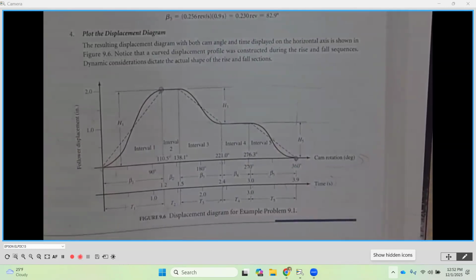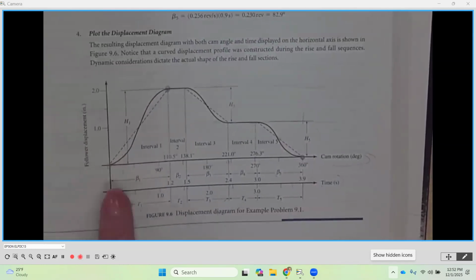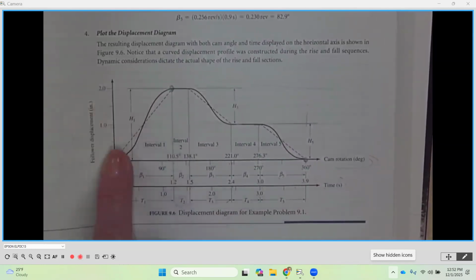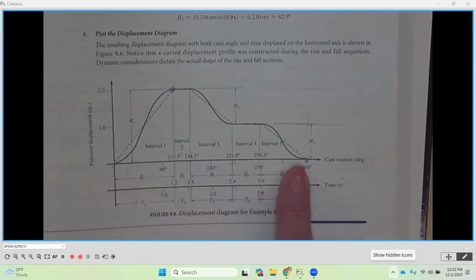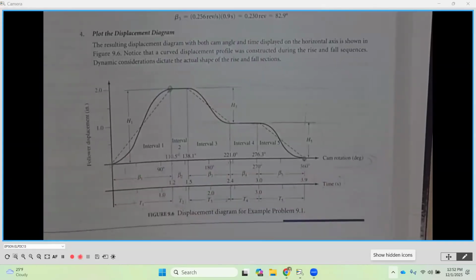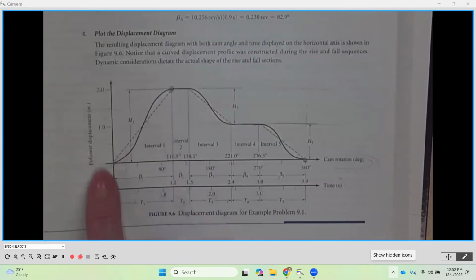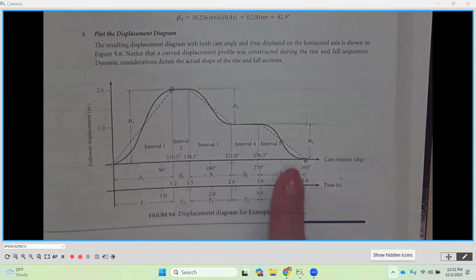All right. Now, proportions. I'm going to repeat this a couple times, but this will be the first time you hear it. As we look at the height here of 2 inches, you might wonder, well, how long should I make that x-axis? You're going to make the x-axis 3 times longer. Okay, so for instance, if I have 2 inches here, I'm going to make this 3 times longer.